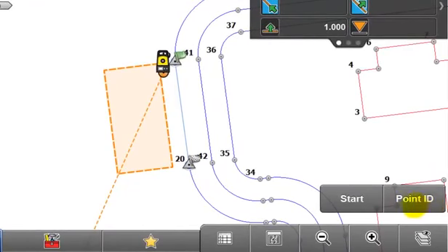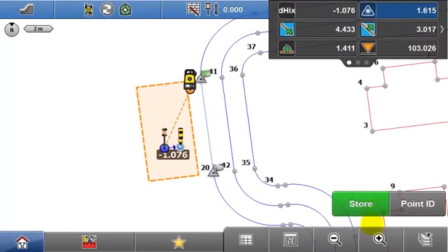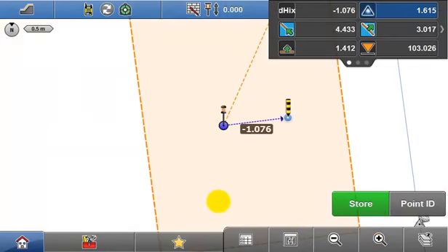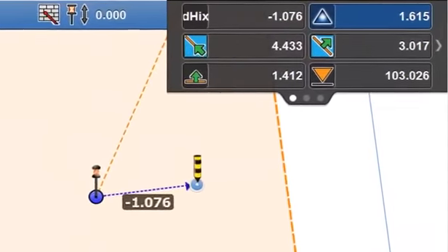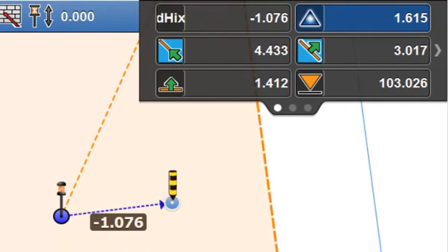Once measurements are initiated, in this example using a total station, the position of the prism is indicated on screen, in real time, along with the intersection point to the reference surface, perpendicular to the initial reference at the current measured height. As well as the prism position being displayed, key measurement data is displayed in the info panel, including the cut or fill value, that is the vertical distance between the current position and the design surface. This value is the horizontal distance between the current position and the reference surface, perpendicular to the initial reference element.